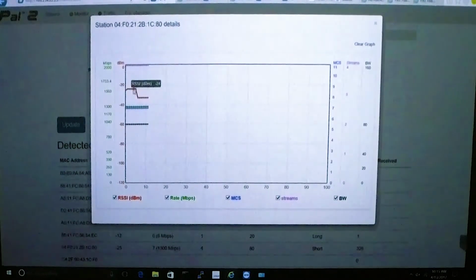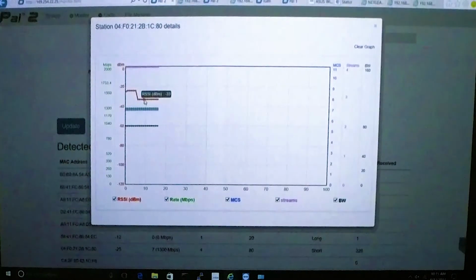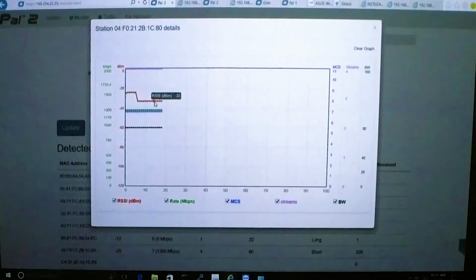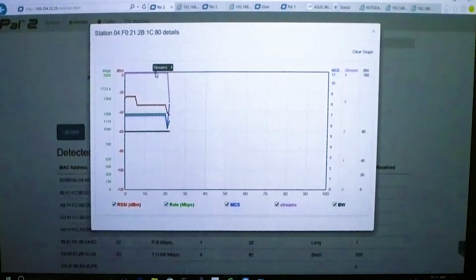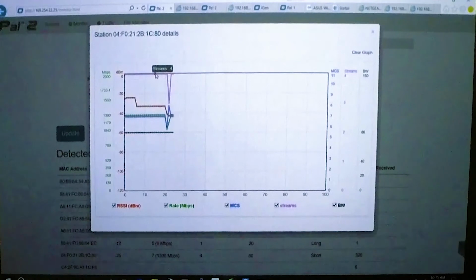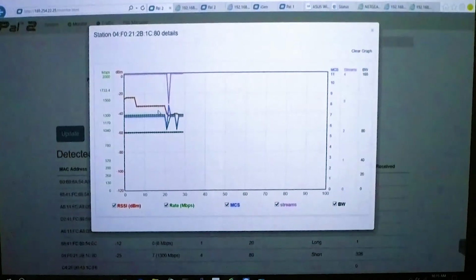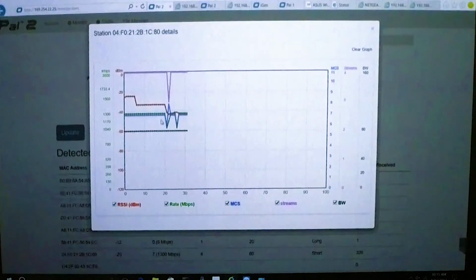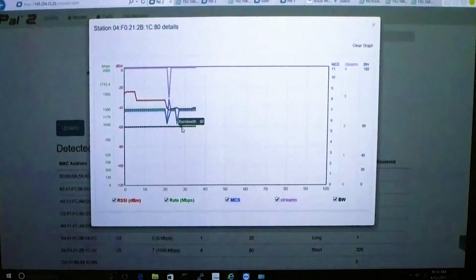So RSSI, as I mentioned, decreases in steps of 10 dB. And we're really trying to run a very fast test here. We have 4 streams in the air, over the air. You guys can look inside later. And okay, so here some adaptation starting to happen as we're dropping the RSSI. This is our MCS. It's also starting to adapt.